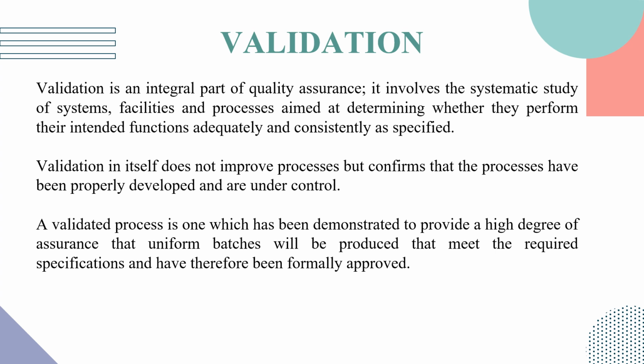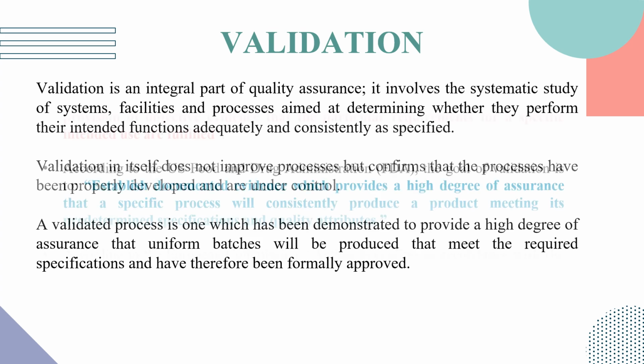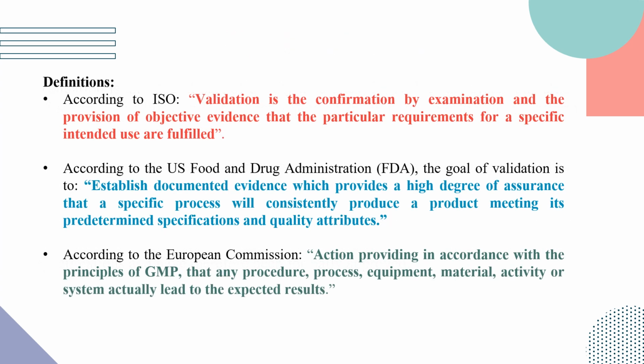It ensures that the instrument is properly installed or not, as per the requirement or specification. It confirms that the process has been properly qualified and under control, a documented verification that the instrument is properly operating or not. And the last is the performance qualification, which is also documented, showing that the equipment operates consistently and gives results within the standard and meets the specification.